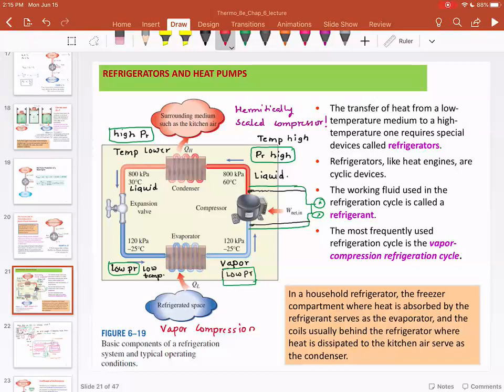As the aircraft is flying through the atmosphere at very high speed, the air impinging on the aircraft structure gets compressed because that high-speed air suddenly loses all its velocity. According to Bernoulli's principle, if you suddenly stop a fast-moving fluid, the pressure is going to shoot up.